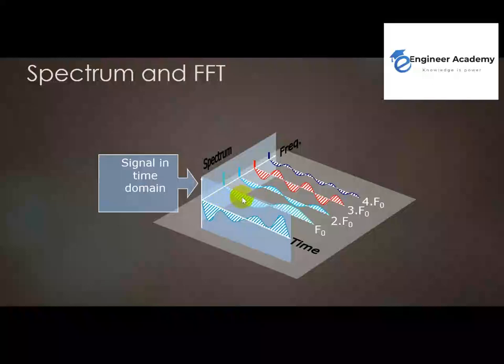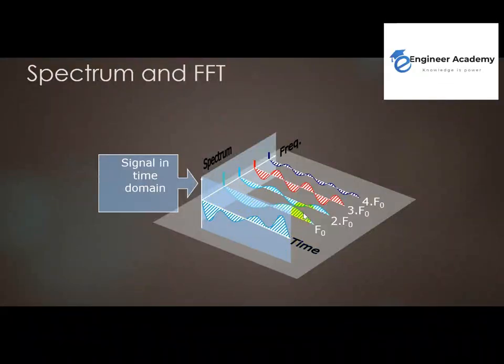We are doing this transformation from time to frequency. Then instead of looking from this side, you start looking from this side. In this side, each time waveform can be represented by just one line and amplitude. This one line at a certain frequency represents the defective part, and the amplitude represents the severity. And of course, all of this has many details we can learn in the course.